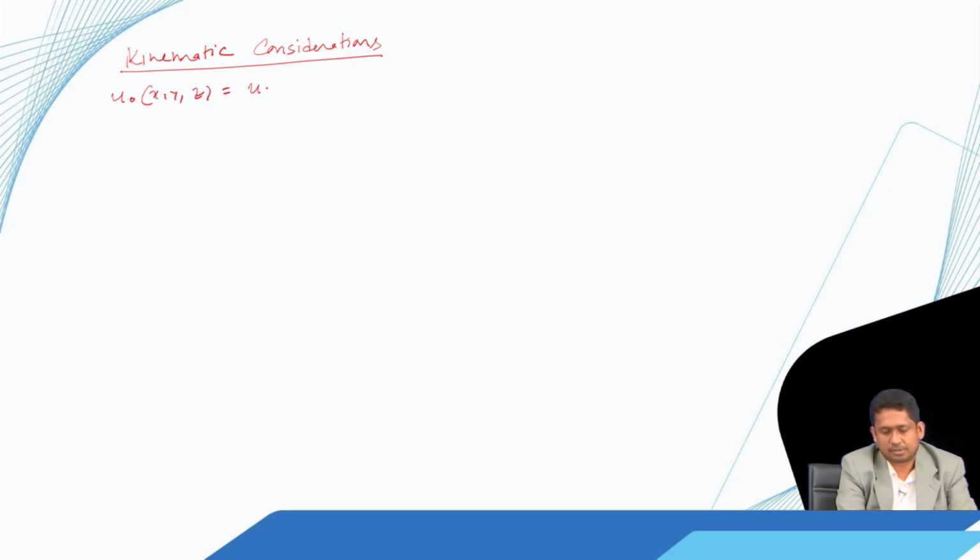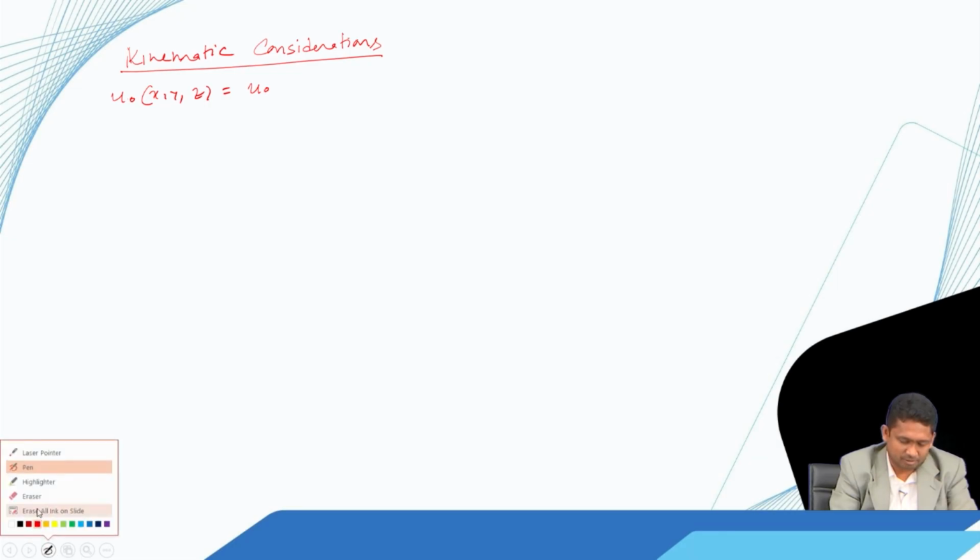So, the kinematic considerations are: u as a function of x, y, z is equal to u0 as a function of x, y, plus z into psi x.